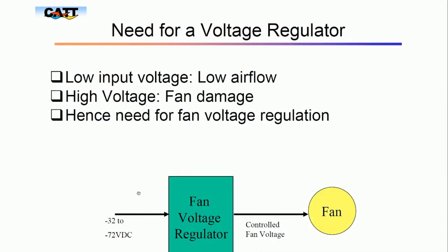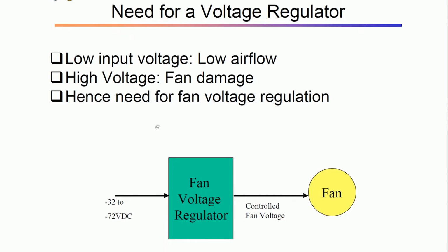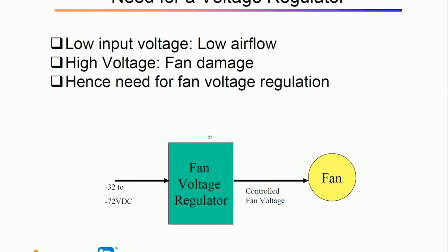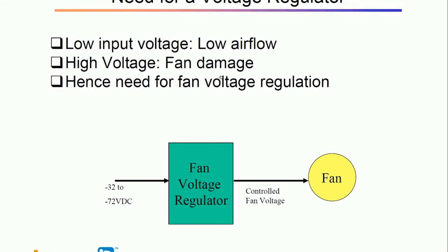So they have all this stuff about a fan voltage regulator typically for this, and contrary to our popular, intuitive reasoning, motors never fail due to low voltage. Not many people appreciate it. They say the voltage was low and it failed, but in fact motors are capable of operating down to a certain lower voltage. Below that they fail, but higher voltage is catastrophic.